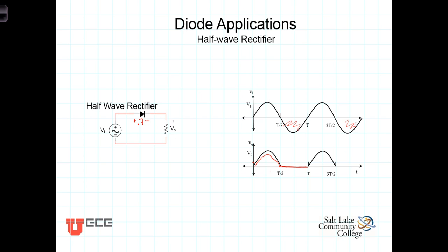At the point that it drops below 7/10 of a volt, the diode stops conducting. So the constant voltage model is going to be closer to what you're going to observe in the lab when we build this up, and the output voltage is going to be about 7/10 of a volt less than the input voltage, and we won't even see that output voltage until the input voltage gets up to 7/10 of a volt.